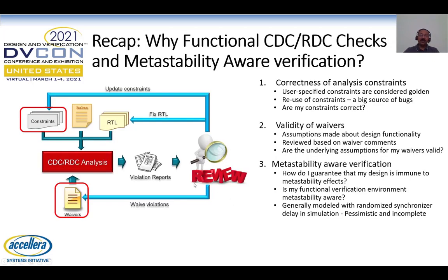Just to recap on why functional CDC RDC checks and metastability aware verification is important, if we look at the major gaps that exist in the current CDC methodology, there are three things. First is the validity of constraints, which says that the analysis is happening under the right set of constraints. Second is the validity of waivers, which means the assumptions made during dispositioning of structural violations are valid.